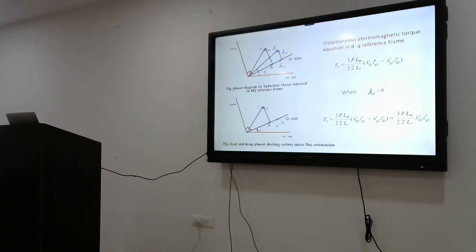The advantage of the field orientation method is that the torque profile is exactly similar to a DC machine after orientation. Performance is the same, maintenance is 0, lifetime is very good, heating effect is less, size is very compact, power density is more. There are a lot of advantages with respect to the induction motor.